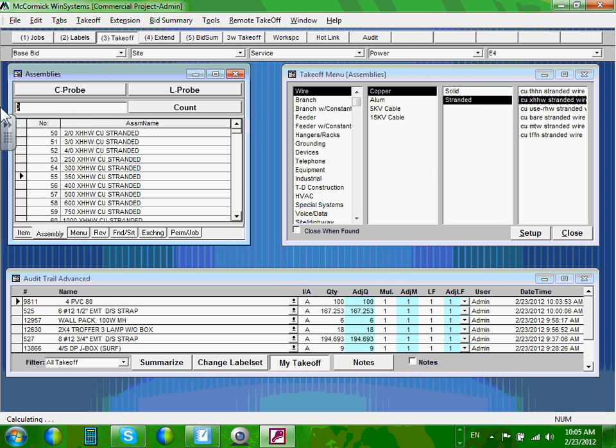And what's the length of that baby? I want to remind you how many conductors and what's the length. So there are 4 conductors. We're pulling full neutral. So whatever the length is, you're going to multiply by what? 4. So let's just say it was 100 feet. 100 times 4, 400. Now some of you say, well, how about termination on each side and all this stuff? You can add another 10 feet for termination on each side. But for the time being, say 100 times 4, 400. I'm going to type 400 here and hit enter. And I have taken all the wires for the feeders. Now, how hard would that be?